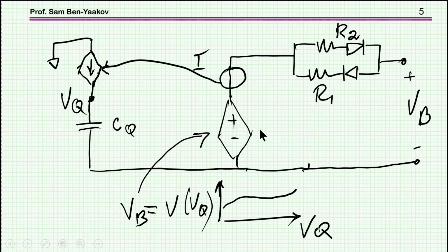So here is the basic model and the idea behind it. We start off with a capacitor which accumulates the current of the battery. This is representing the battery. This is a voltage dependent source. So we measure the current, duplicate it here, and feed it to the capacitor, which integrates the current, so we get here a charge as a function of time. Now this voltage dependent source represents the battery. Given the charge, you have a certain voltage. That is, here we have the dependence between the charge, the state of charge, you might say, and the voltage of the battery. This is this open circuit curve, the rest voltage. Now, we can make a voltage dependent source that will behave like this, and we'll see it in a while.